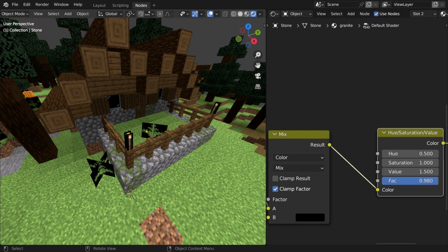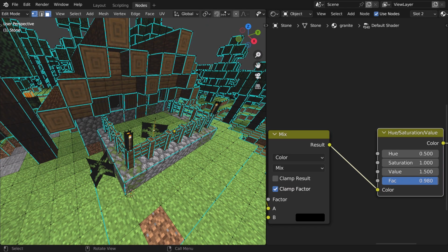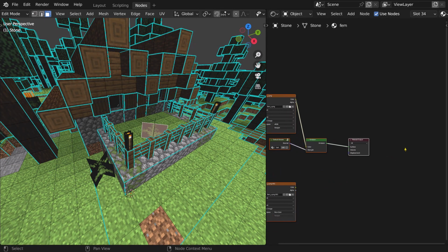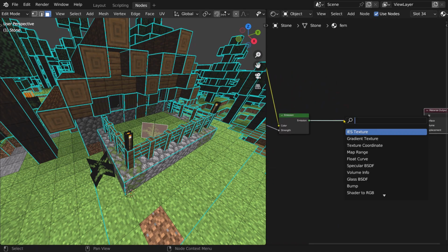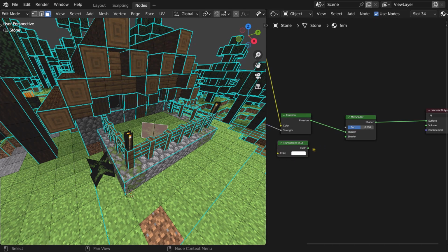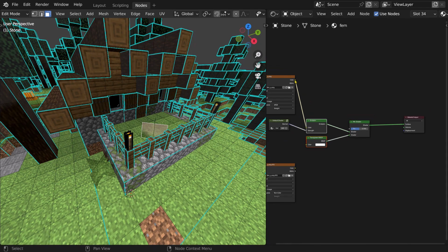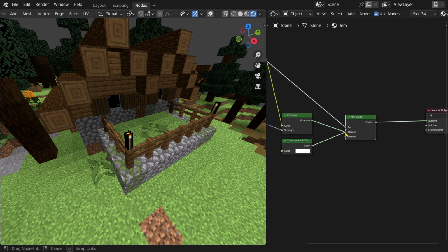Alright, let's deal with image transparency now. Switch to Edit mode. Select one of the images, textures, or faces that need transparency, such as leaves or glass. Add a Mix Shader node, then connect it to your materials to get rid of those annoying black areas that appear in the textures and accurately control the transparency clarity. Connect the alpha output from the image to the factor of the Mix Shader node. Well, to fix the issue that just appeared, try swapping the materials here.